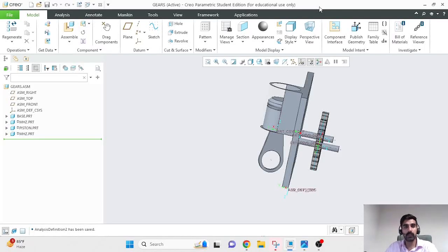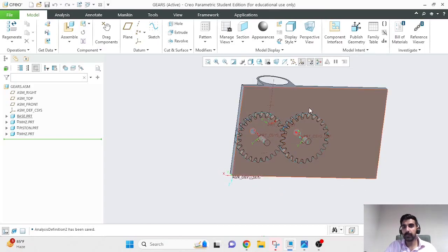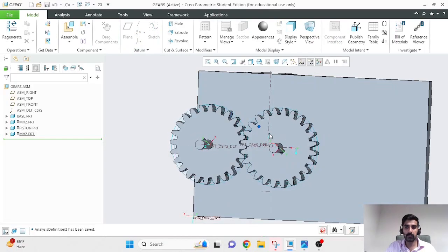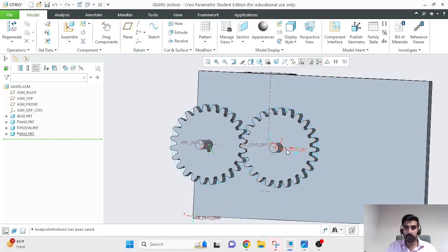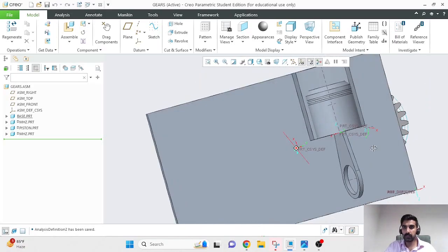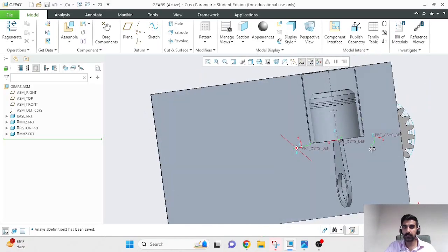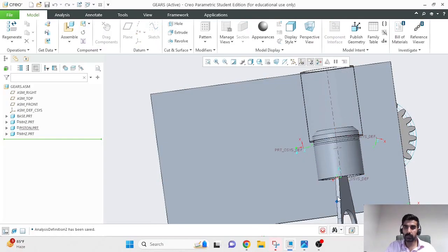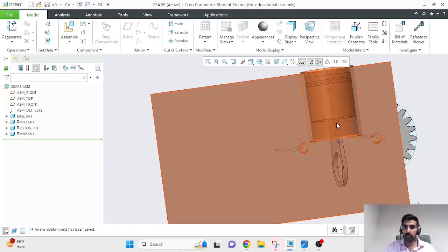In this video, we will learn how we can use Creo Mechanism to actuate different movable assemblies. This is an assembly that we've made in a previous session where we have two gears mounted on pin joints and a gear connection between the two spur gears. When we move the first gear, the second gear moves as it should based on the mechanics of the gear train, and over here we have a slider connection where this piston can reciprocate up and down within prescribed bounds.